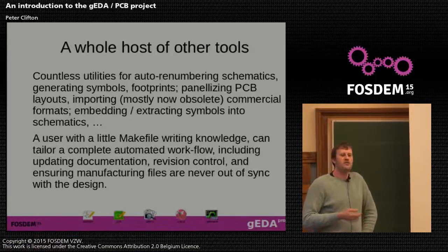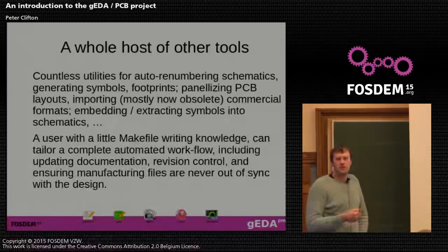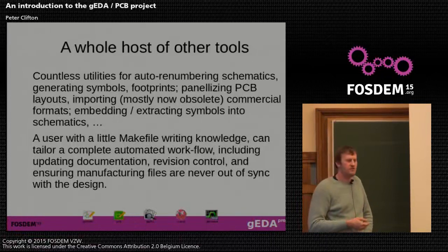And in some of the projects I've done with circuits where I've used hierarchical blocks, I've actually used a renumbering system there. So we start with a master schematic, and you repeat that layout 8 times in a makefile with updated refdes.